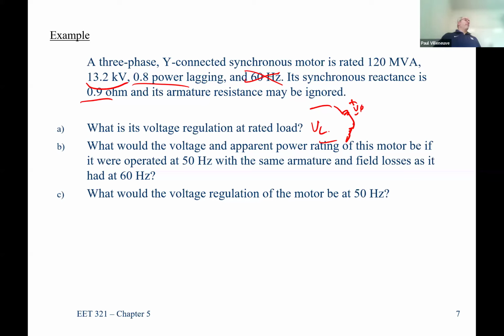All right. So 208 is actually fairly common in industrial facilities because everything that they have is 3-phase. So I'm not going to put a single phase transformer to feed some loads. I'm going to run a 3-phase transformer because I want my load to be balanced. And then I'm going to distribute that 120 volts wherever I need to. If you go over to the new engineering building in Barrows, called New Barrows, it's 20 years old, but they call it New. They have a bunch of outlets everywhere. Everything inside the building is fed from a 3-phase transformer, and they just move the loads around as necessary.